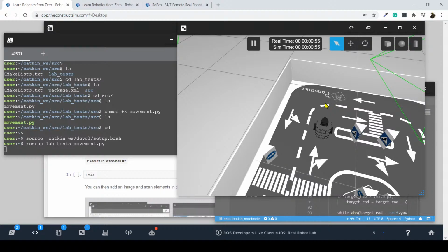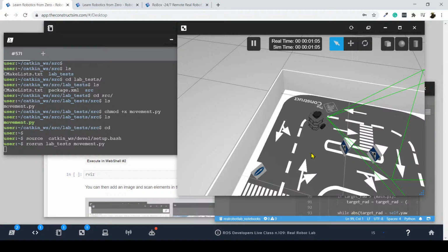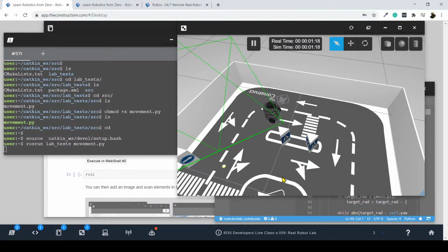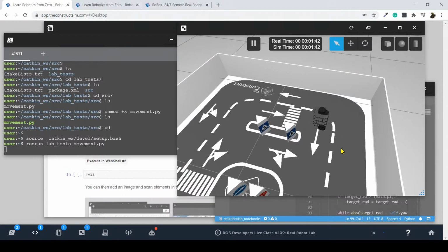Then I should expect that somewhere around here the robot stops and turns 90 degrees to the right. There we go, it stops, it turns 90 degrees to the right. And it keeps going. There we have it. So it keeps moving forward. Now the distance from the laser to the obstacle is higher than 45 centimeters, so the robot keeps moving forward. Then once this distance gets lower than 45 centimeters, the robot is going to stop and rotate 90 degrees to the right. Makes sense?